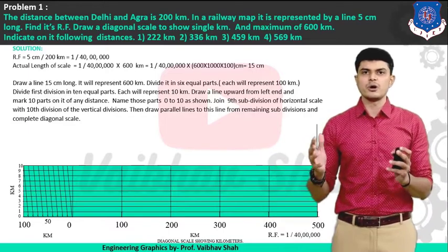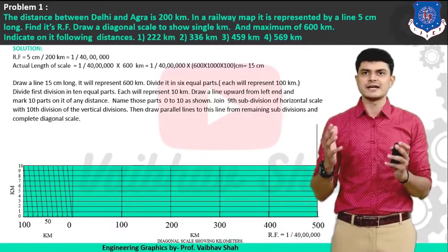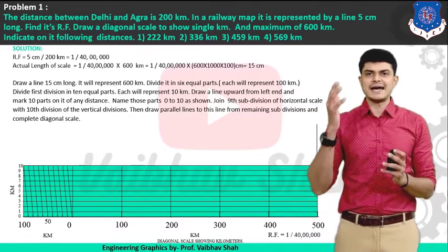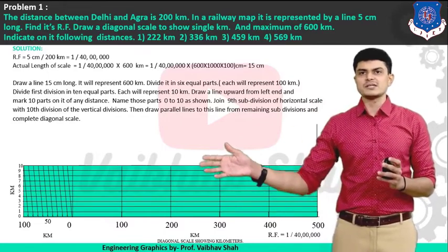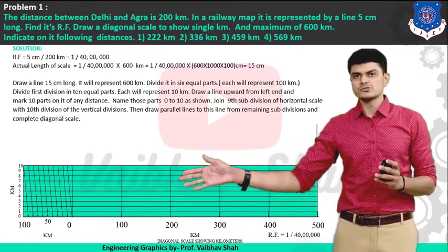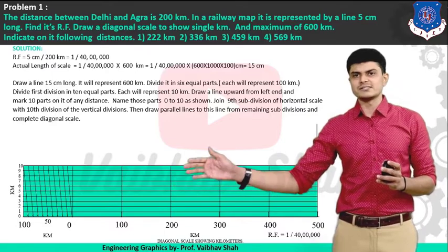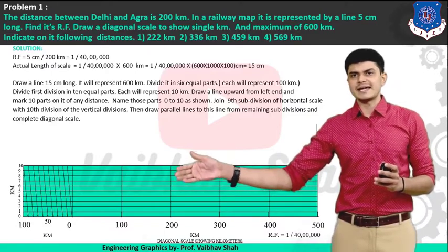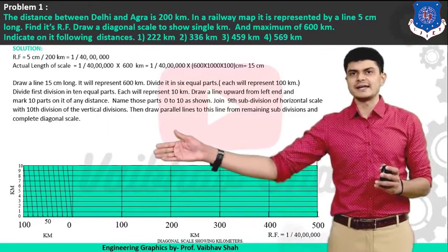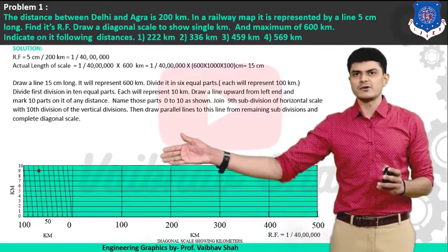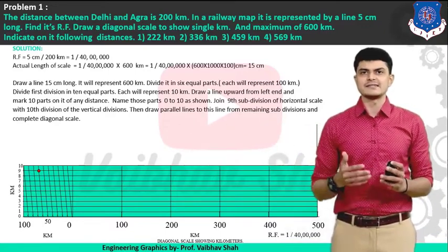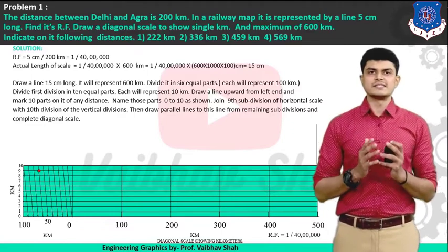So now you have to go up by your 9th division because we are going on the tertiary scale now. So in tertiary scale we will be having 9. So you have to go 9 points up on your tertiary scale starting from your 60 division at the bottom 0. So on 60 division just on the left hand side of your secondary scale you need to go up 1, 2, 3, 4, 5, 6, 7, 8 and 9. So you will be having this point on the 9th division on your 60 line of your secondary scale, and this is nothing but your 69.